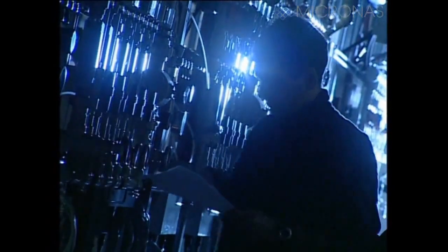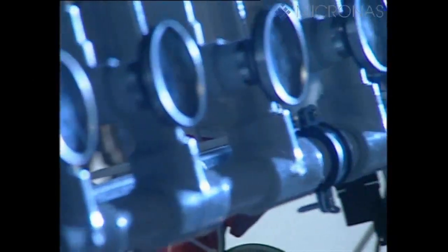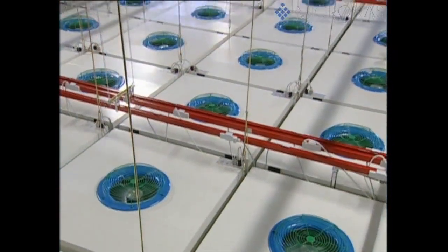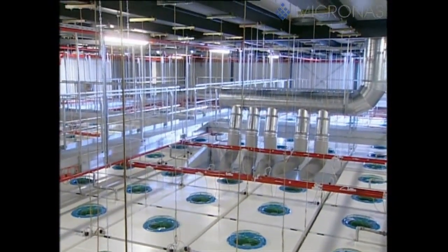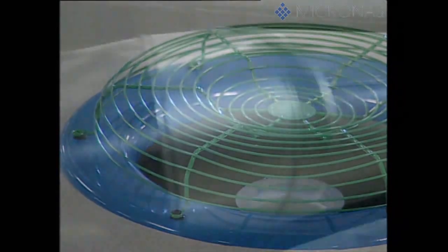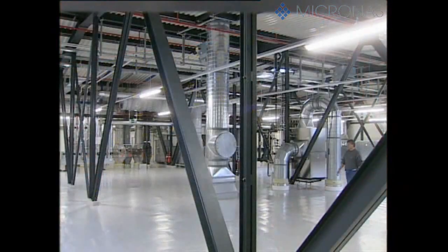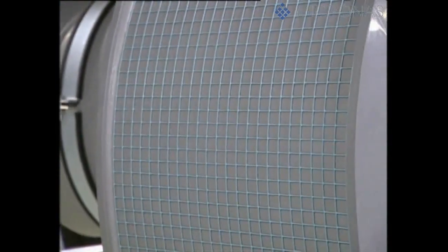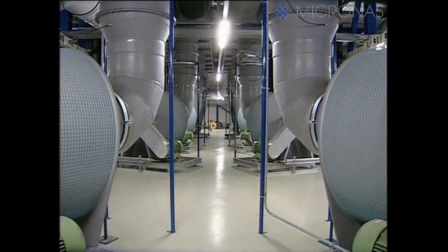Extremely stringent requirements are placed on a clean room for the manufacture of integrated circuits. Extremely clean air, no structural vibrations, a stable temperature, a uniform air supply, plus a great deal more. All this calls for elaborate installations in the building. The circulating air filter systems ensure that there are no particles in the clean room and that a laminar airflow prevails without any turbulence. The volumetric airflow is about 700,000 cubic meters per hour, which means that the air circulates 400 times an hour. At the same time, the air in the room is kept at a constant 22 degrees Celsius throughout the year, with an air humidity of 45%.